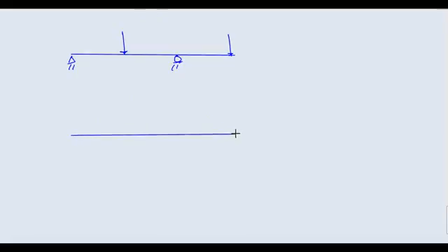Suppose I am drawing the bending moment diagram. What I will do is, suppose I want to fix this support, I will fix this support, and now you will have some reaction here. Suppose this is force number 1, this is force number 2, and this is force number 3. Now simply draw the bending moment diagram of these forces, assuming that this support is fixed.